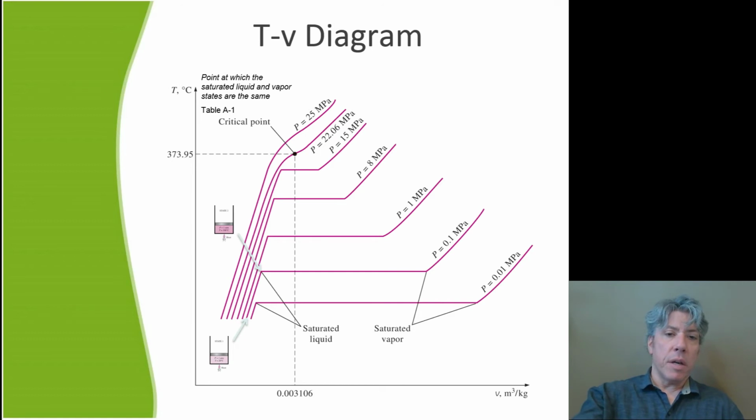If we continue, now notice one thing that happened here is the temperature went up and the specific volume did change a little bit. It got a little bigger, a little less dense. Not much, but some. Enough that it's something I have to contend with in my heating system. I've got 1,000 gallons of water storage. It's not potable water, it's just water for holding thermal energy. And that water will expand as I heat it. It starts off at about ground temperature, 50 degrees, and goes up to about 200 degrees using the wood-fired boiler